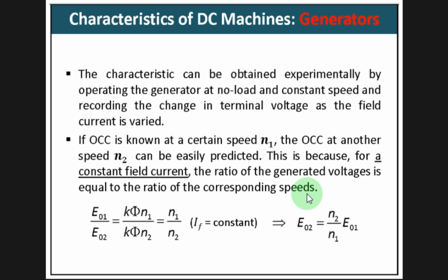So when the field current is constant, the generated EMF is totally dependent on the speed of rotation of the generator at no load.